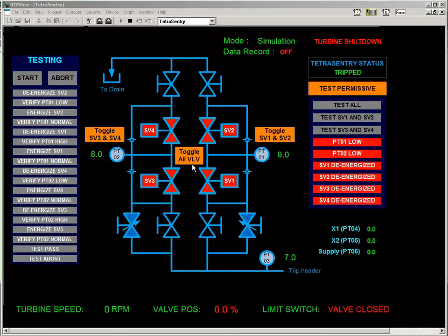If we activate all of these valves, we'll see that the trip header pressure comes up when the valves close. What you see is trip header pressure of about 160. The pressure at the cavities between the serial pairs of valves runs about half of the trip header pressure.